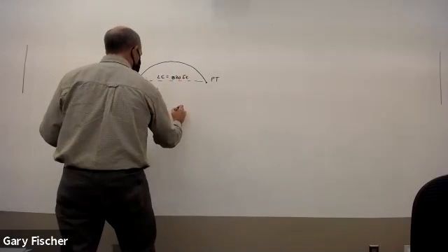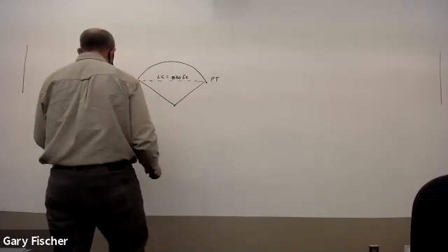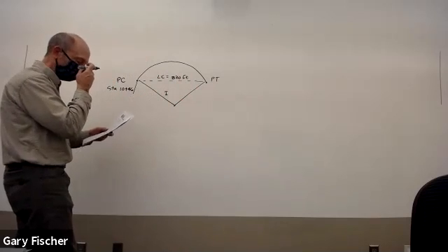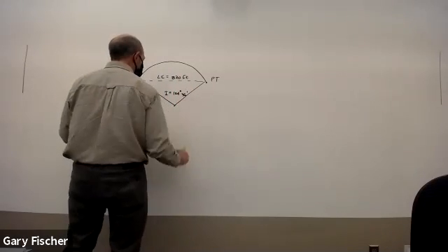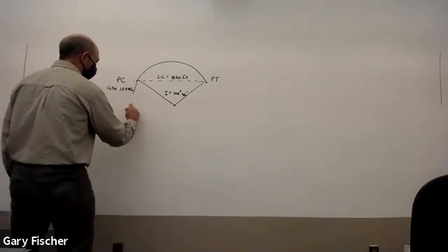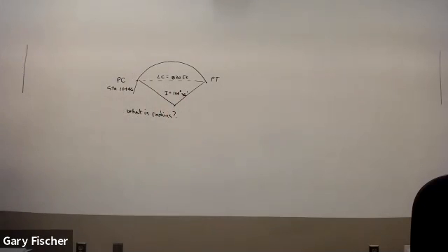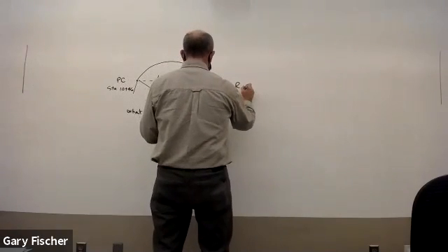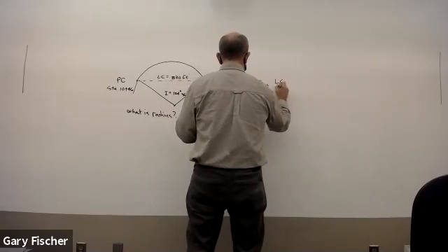And they identify this point out here, and they measure out this angle I, which is the intersection angle, equal to 104 degrees 36 minutes. And it asks you, what is the radius of the curve? Now, I'm pretty sure that if you go into the reference manual, they give you these formulas. The radius of the curve times the sine of I over 2 is equal to the length of the curve divided by 2.